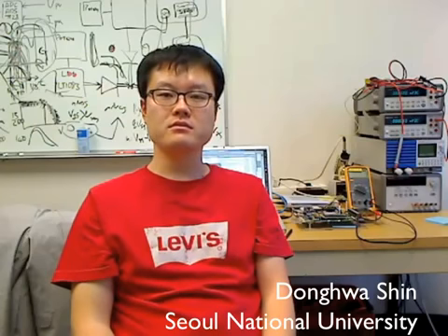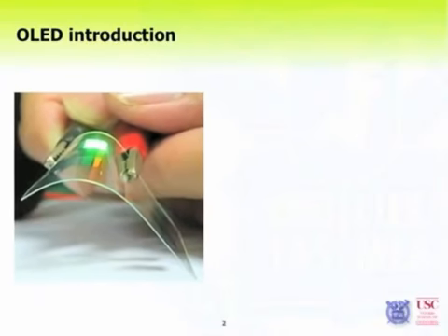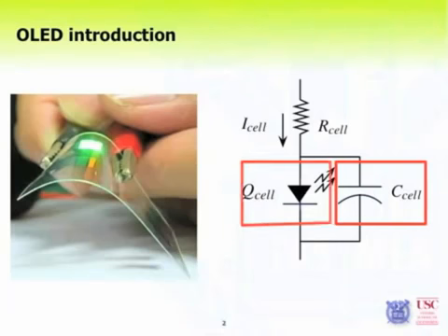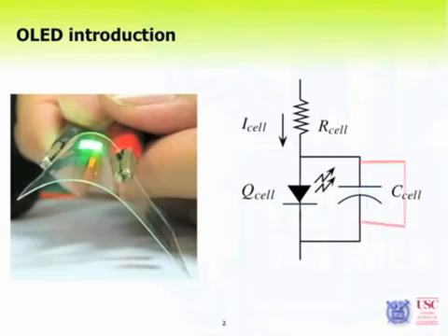This is a typical structure of the OLED unit cell. Light emitting diode is implemented by using the light emission material layers. The OLED device has a large area, but the thickness of the organic layer between the electrodes is very thin, so OLED cells have a large internal capacitance. OLED cells have a resistive component for each layer between anode and cathode. The dominant resistive component is the transparent indium tin oxide layer. The parasitic resistor is in series with the internal capacitance.